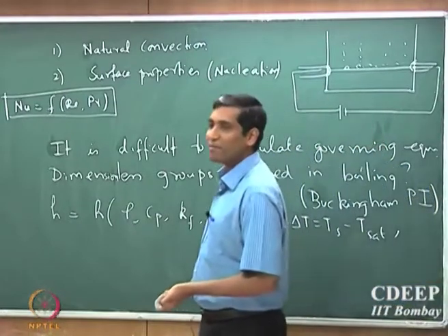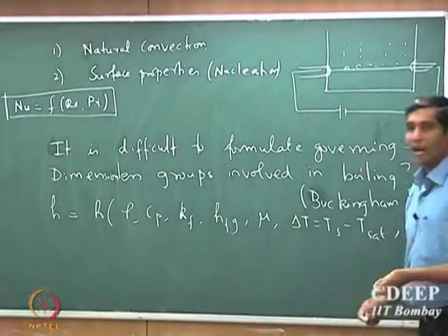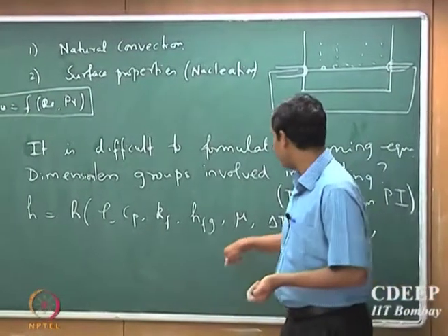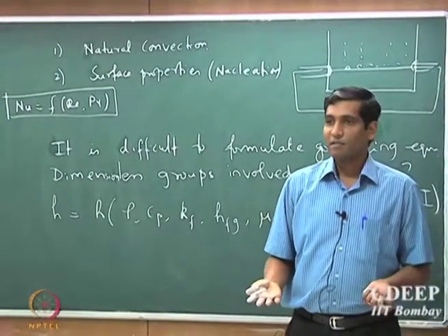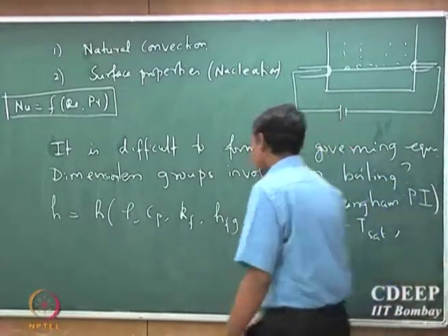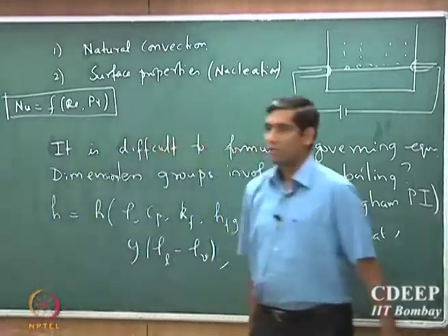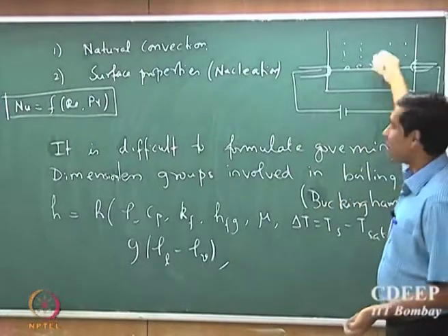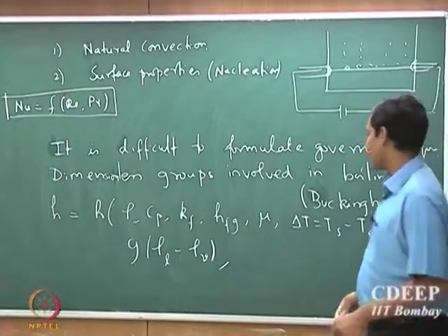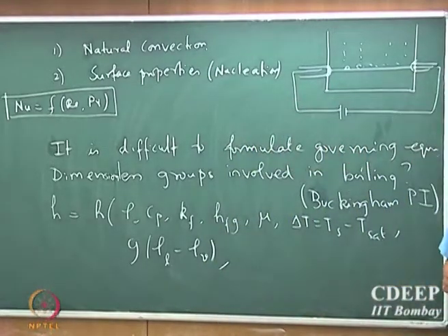Particularly when we are looking at boiling, assume that the fluid is actually at saturation. So that's okay. What else? So natural convection. We said viscosity, but what else? Gravity, right? Somehow the buoyancy has to play a role here, right? So it will be g times (rho liquid minus rho vapor). That tells you the body force difference between different locations in the fluid, and that exhibits the buoyancy, right? So how many are there? 1, 2, 3, 4, 5, 6, 7. What else? That's it.